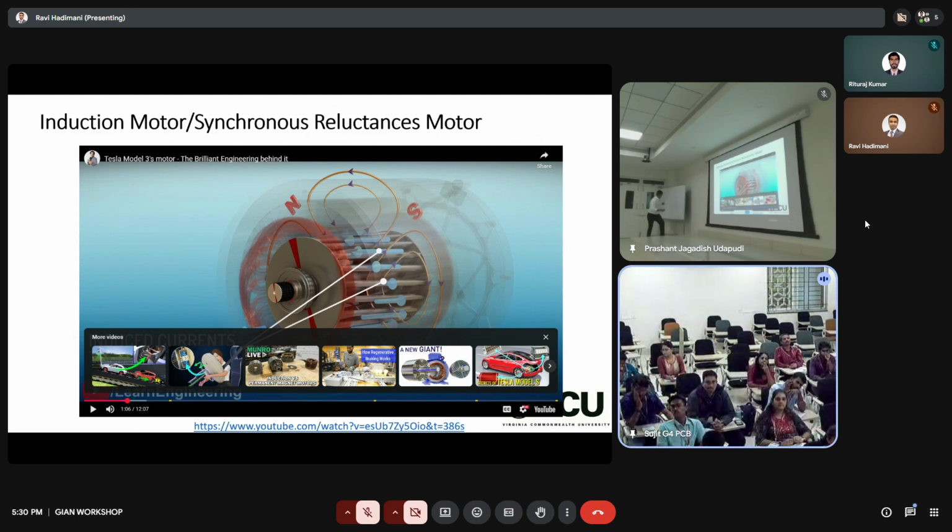Basically, the area in this curve is lost energy if you cycle continuously. In permanent magnets, we don't cycle, but in soft ferromagnetic materials, if you magnetize and demagnetize them, then the area under the curve is lost as heat. So that means if you have higher coercivity, you are going to generate a lot of heat. So in induction motors, those are soft ferromagnetic materials. Okay, so